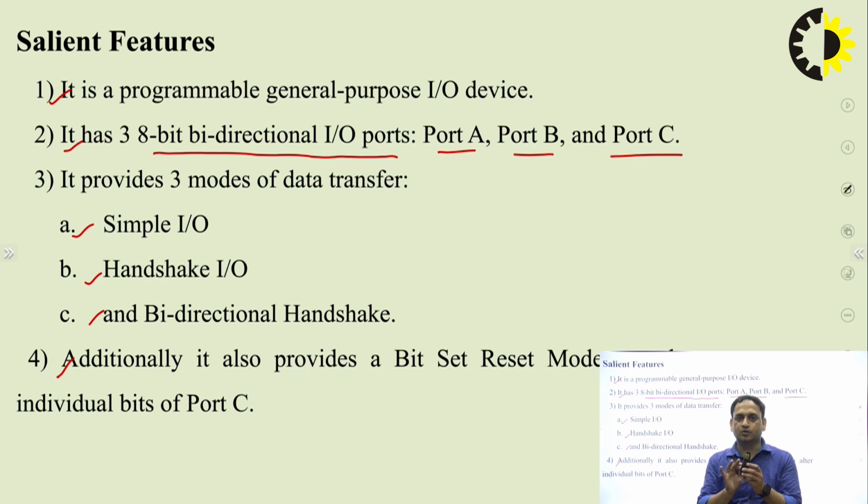This architecture is common to different ICs, just like 8237, 8255 which we are going to discuss, and 8259 which is the cascade interrupt IC. On the right hand side of the IC in the diagram, we see the lines which carry port A, port B and port C.